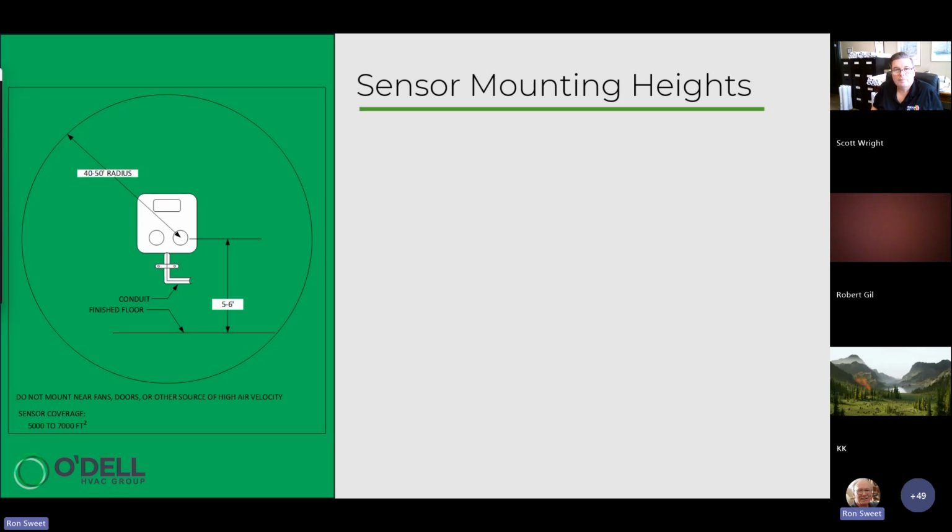Decimal 1, decimal 5, decimal 7. And we bring on the ventilation at decimal 7 ppm for nitrogen dioxide. Immediate danger to life for nitrogen dioxide, 13 ppm versus the 1200 ppm for carbon monoxide. 13 ppm, immediately dangerous to human health. So monitoring for those gases in the breathing zone, as well as all other toxic gases, so that you can protect human beings by utilizing dilution through ventilation is critical.